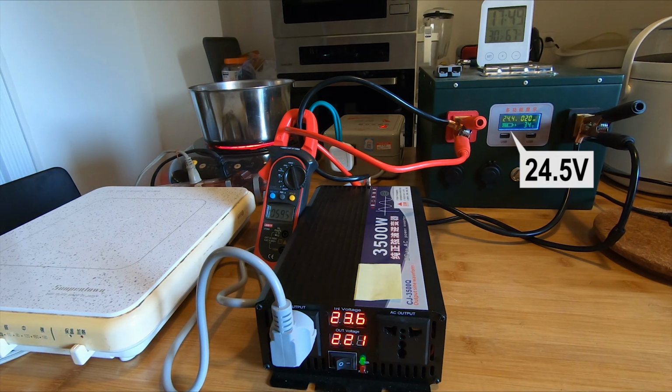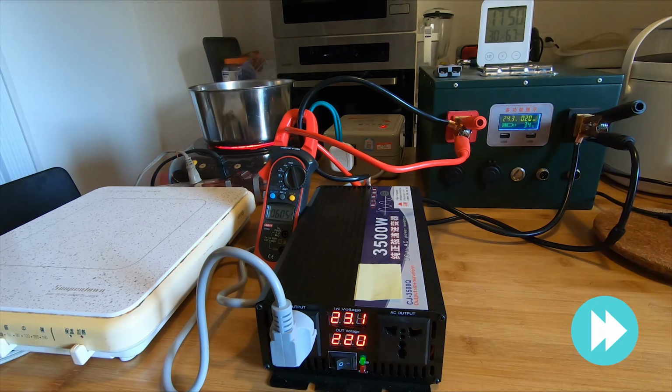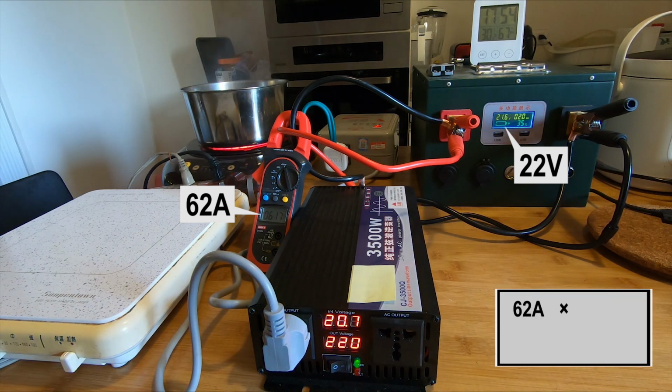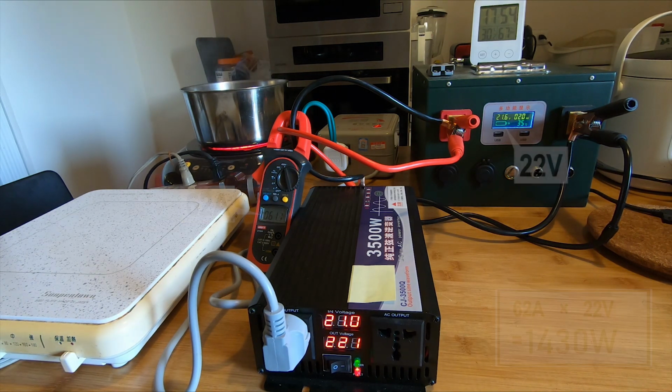Now, the battery voltage is 24.5 volt and the output current is about 60 amp. The power output to the inverter is about 1470 watt. After another 5 minutes, the output current is now about 62 amp and the voltage drops to 22 volt. The power output to the inverter is about 1430 watt. Within a minute, the voltage continued to drop to 21 volt. The inverter stopped automatically after sounding the low voltage alarm.